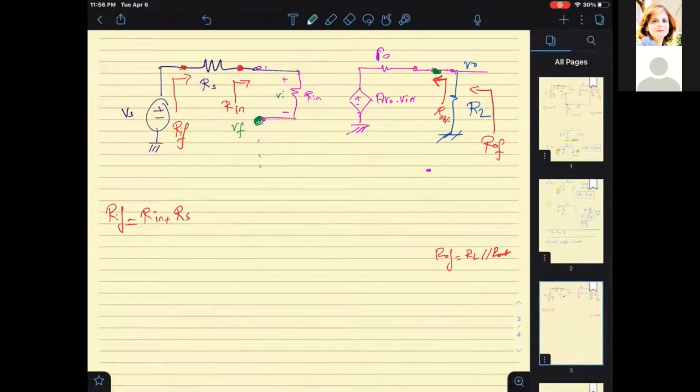So the beta block was connected as this form of feedback. This was R2, this was R1, and this was the feedback. What I do is I remove this connection here and I replace it by a resistor R22, and also I remove this connection here, but I place a resistor R11 in series with the whole Vs-Rs-Vn loop